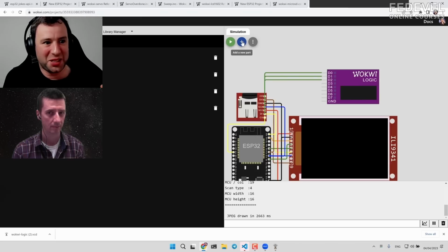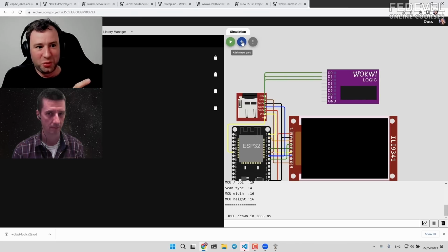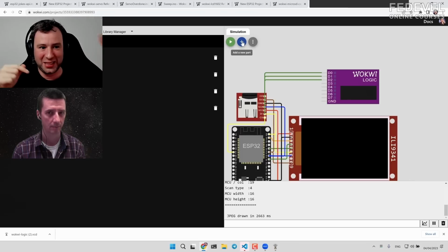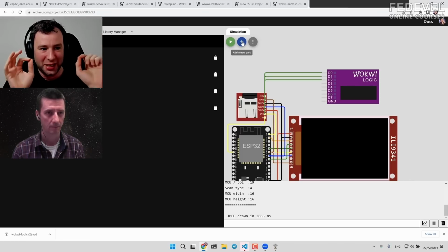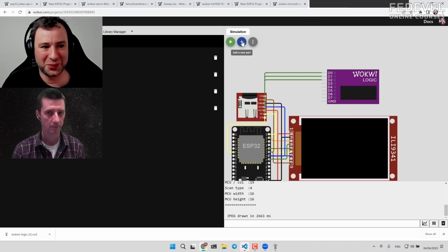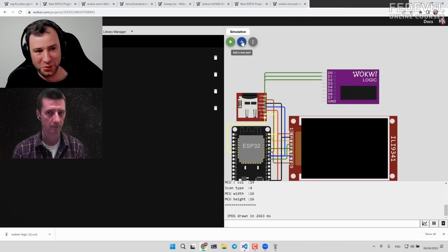But just imagine, in 2 seconds it got to 1 million, so by the time you display the JPEG, it's like 20, 30 million signal transitions, and every single one has to be right for this to work. That's why I'm really grateful to have all these tools inside the simulator and PulseView to be able to debug it when I'm building it.